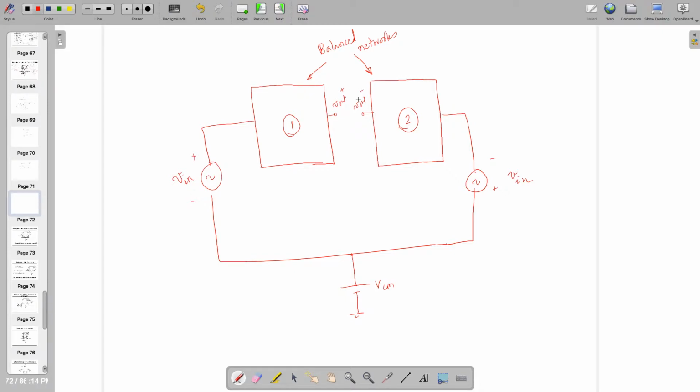But this kind of amplifier is actually a pseudo differential amplifier, where there is no relation between these two balanced networks. However, when you are connecting these two with some point, with some current, this makes sure that the common mode voltage is not going to affect these two balanced networks in terms of current determination.